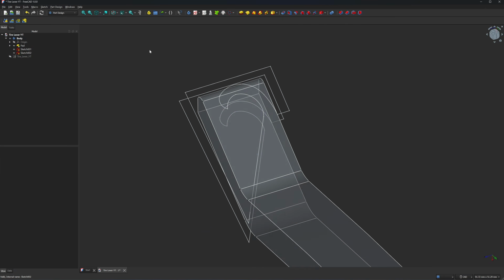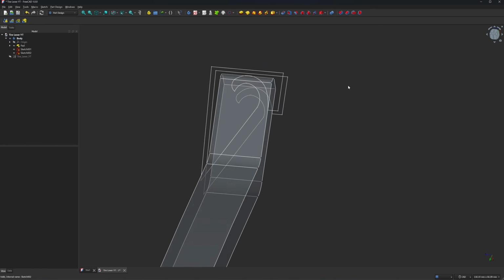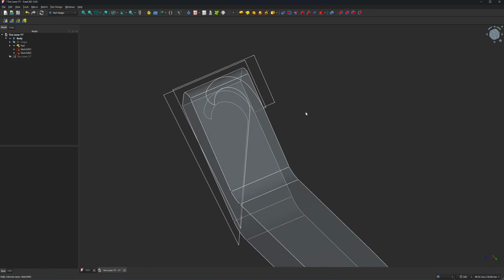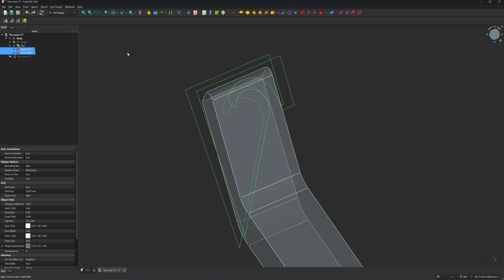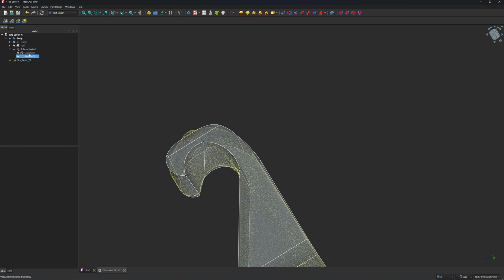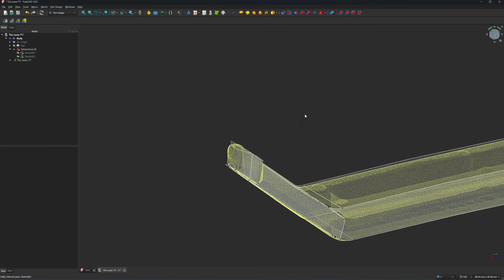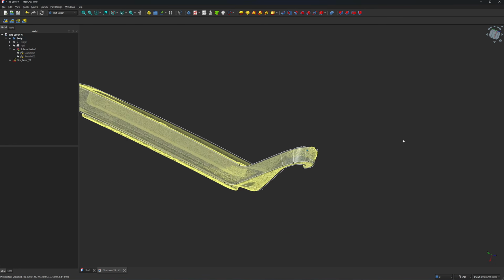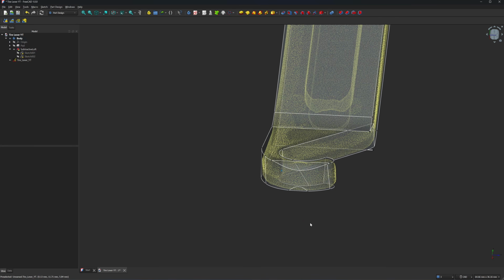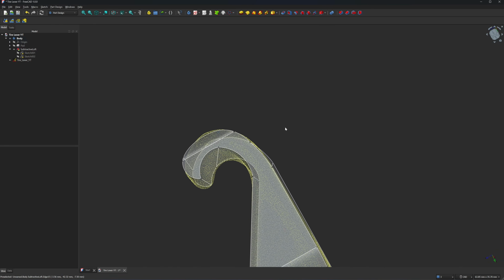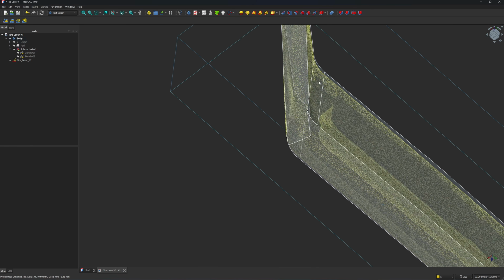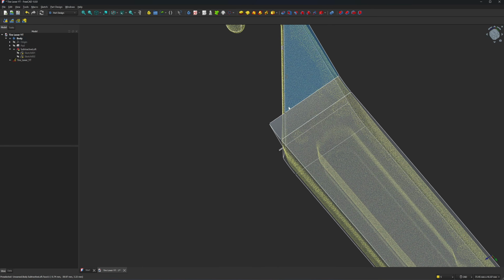Let's turn the path on. So with this same number of lines, I can do a loft cutting with the two sketches. I do this by clicking on the two sketches, click on this subtractive loft. After loft cutting, you still can adjust the position of the curve. It's quite difficult to do because the object has a round corner, so it's quite difficult to see the exact location.